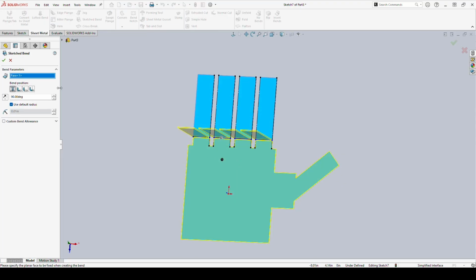Fast forward a little bit there. And you see that it is wanting to bend all of these, even though it shouldn't be bending this guy and this guy because those are my construction lines, which shouldn't impact anything as far as our sketch or extrusion. This happens every so often with extrusions, every so often with other pieces where SolidWorks is just a little bit behind the fact that those are construction lines. It doesn't quite catch it, and it should.